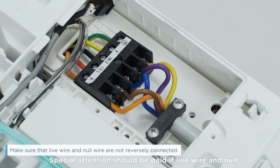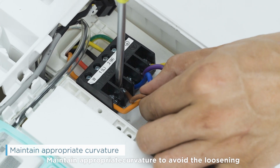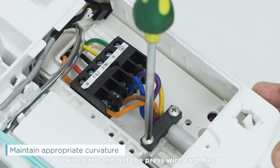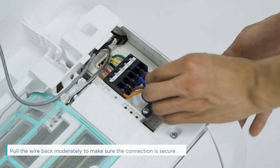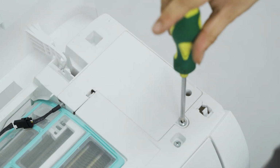Special attention should be paid if live wire and null wire are incorrectly connected. The air conditioner may not work regularly as a result of malfunction. Maintain appropriate curvature to avoid the loosening of the wiring terminal under stress. Compress the connecting wire with the press wire card and get the press wire card fixed. Pull the wire back moderately to make sure the connection is secure. Mount the cover of the electric control box.